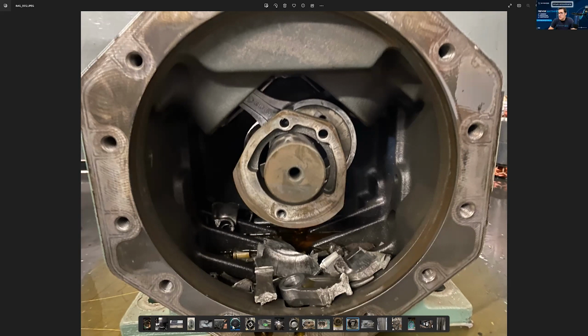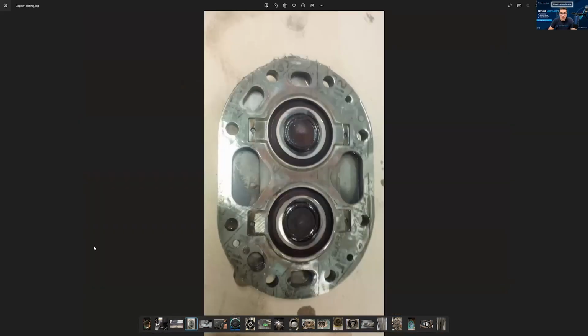Yeah, and you're talking about contamination, like when you take a look at scrolls, hermetics, even semi-hermetics, and you see what you see here, right? This is caused from contamination, right? Moisture in your system causing breakdown of that oil. Mineral oil, they used to see it when you had a lot of overheating. You'd get some of this looking like this, but POE oil is moisture. A lot of moisture and some heat, and it goes to all the hottest parts.